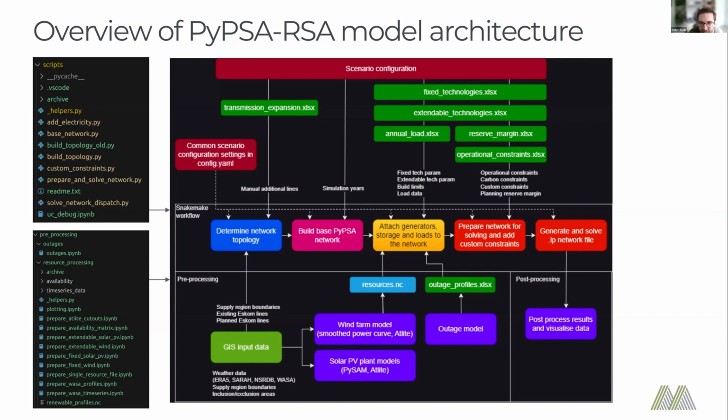Some of the literature and thinking is that instead of this brute force planning reserve margin, you have to run multiple weather years and look at more statistical outage probabilities, etc. So just meeting your planning reserve margin under the current criteria is not a 100% guarantee anymore that you won't have load shedding. So that's definitely an area of ongoing work. But at the moment, it's captured just in a planning reserve margin.